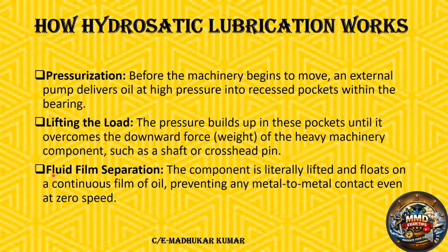Third, fluid film separation. The component is literally lifted and floats on a continuous film of lube oil, preventing any metal to metal contact even at zero speed. The most important thing is that even at zero speed, the separation is already created. And due to this, we have the term hydrostatic lubrication.